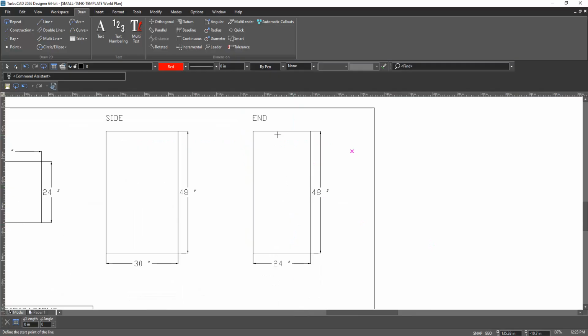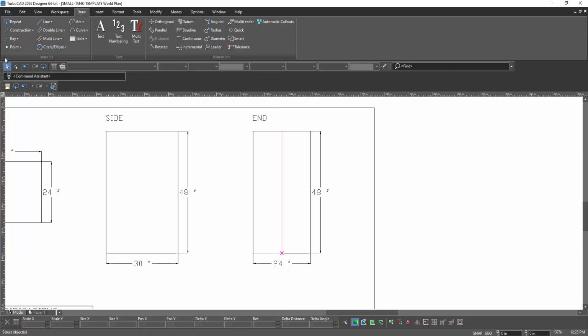And so just click one time with your left mouse button, drag it all the way down there. Before you click again, look down in the left side, make sure that says 48" by 270, and if it does, just click again. Now you're still on the line tool. You can go ahead and hit escape on your keyboard, and that'll get you out of the line tool. Now let's go up here and hit our arrow.